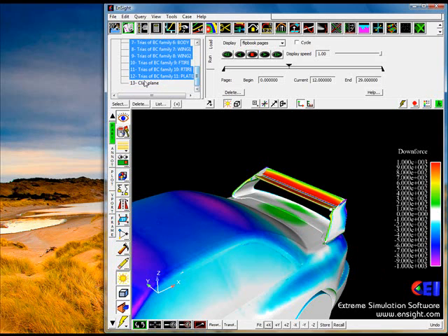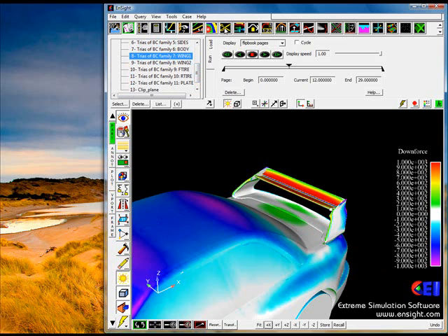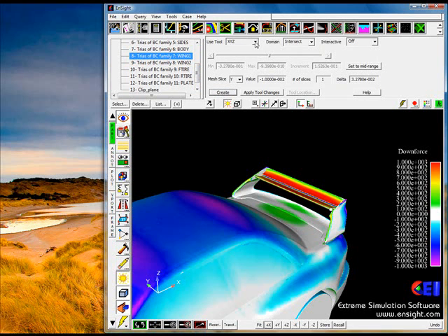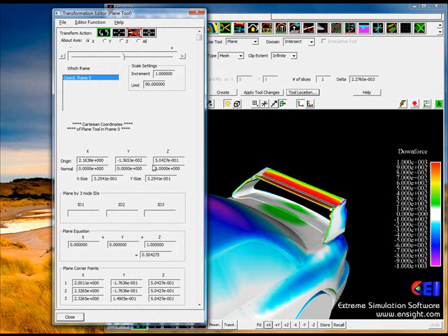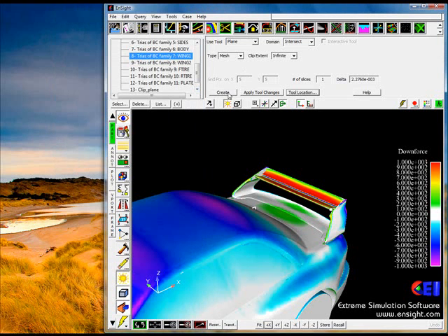So the first thing we'll do is select the wing element that we'd like to take a section cut through, and we shall cut it with a plane. We can use a tool location here to specify the location of the plane. We'll make it very near 0. I should make this 3. And we'll make the normal in the -1 direction. Okay. So we've got a plane created, approximately where we'd like to start our section cut.